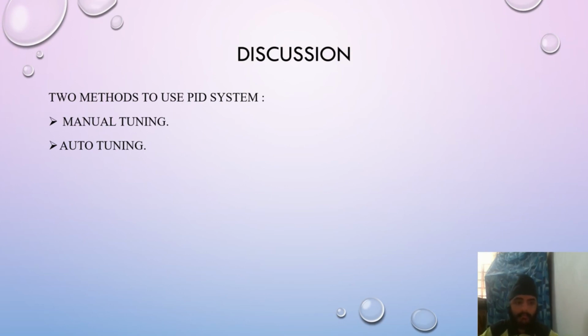Auto tuning method of the PID system is much more efficient. We are able to perform a step test and gain the controller response automatically. Once the process is started, the model may not always be accurate, but it certainly brings out a similar value of the output desired for the DC motor system. The method is usually done by simulation in an application like Simulink to gain the proper desired value.